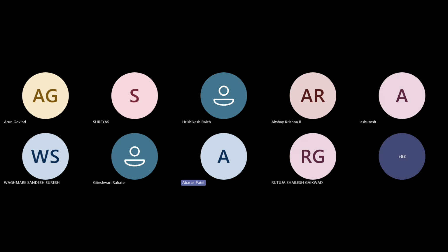3.03 fuse. For the fuse specifications you need to mention, you have your fuse in your battery pack and in your controller. Is it a delay type or instant blow, and what are the current ratings? It is 180 amps, 125 amps. What is the rated voltage for that? Let's say 58.8 volts, 48 volts. So you have to mention that.